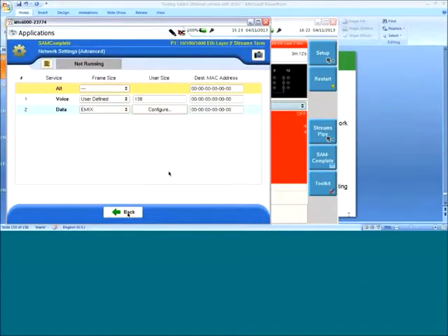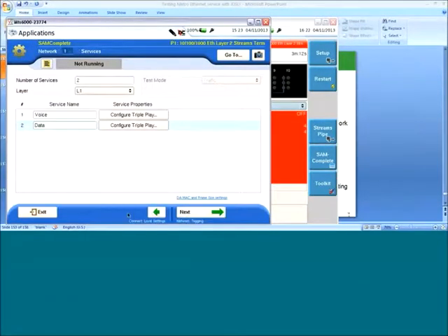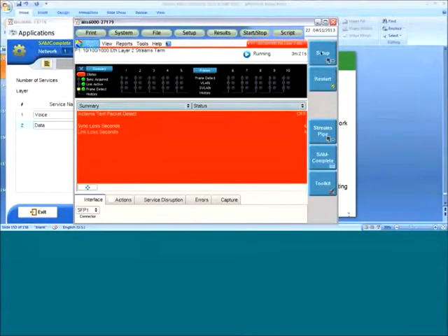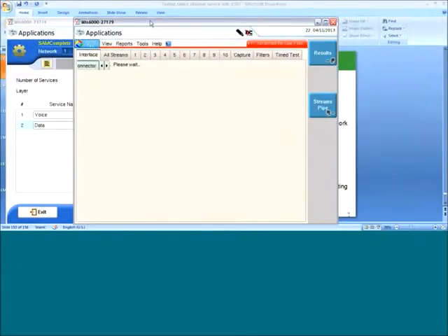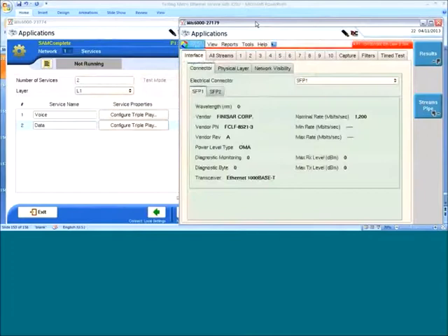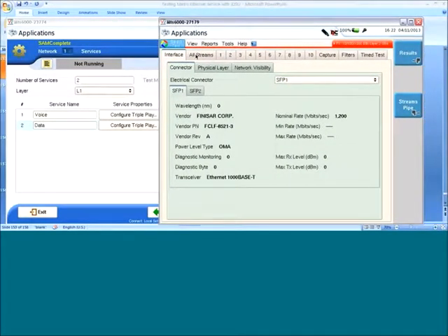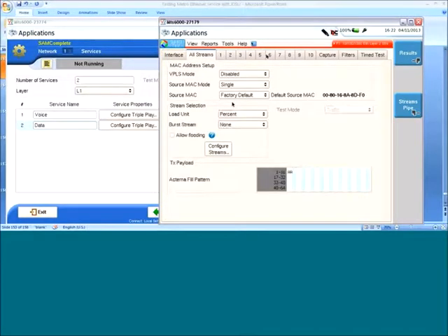All right. So let's go back. Okay. And of course, the destination MAC information. Let's go get my MAC information from here. So guys, the reason I'm actually getting the MAC information is not because I don't want to do the auto discovery, it's that there's several T-BERDs in that network. So I may loop back a different equipment that I don't want to loop back. So we're going to set up the MAC address manually.